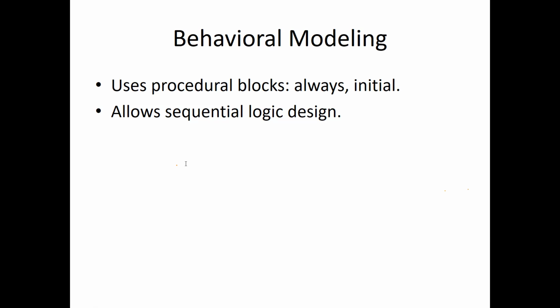So the sequential module, with input and output declarations. And how can we write the procedure? Always at the rate of, here we are using sequential logic, so we always have to use the clock. So always at clock or reset.